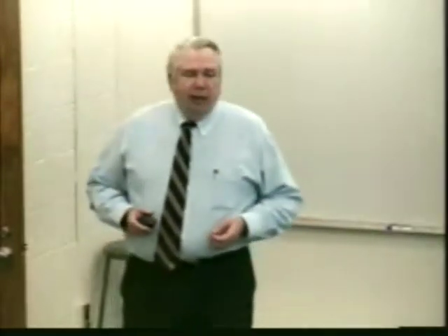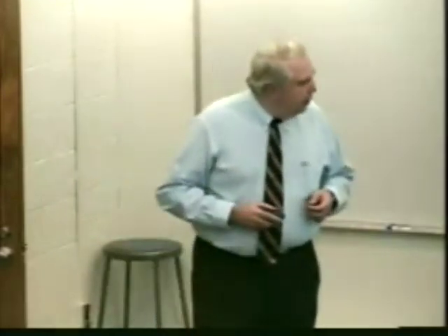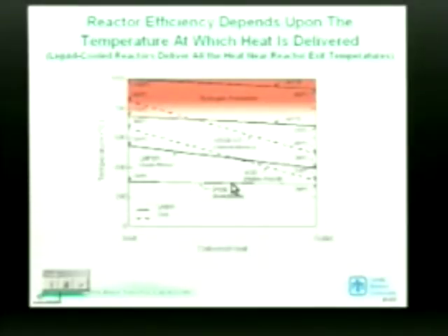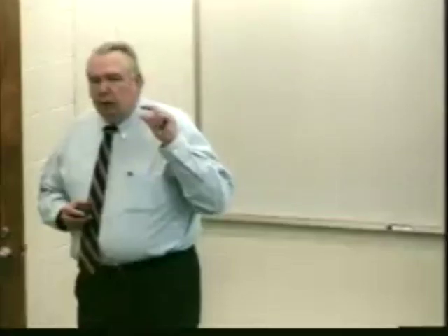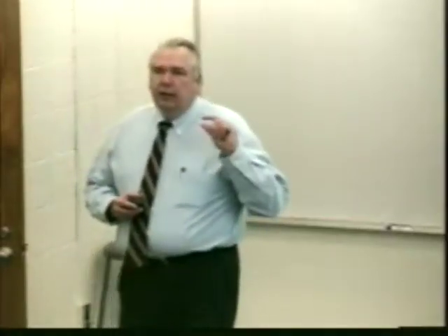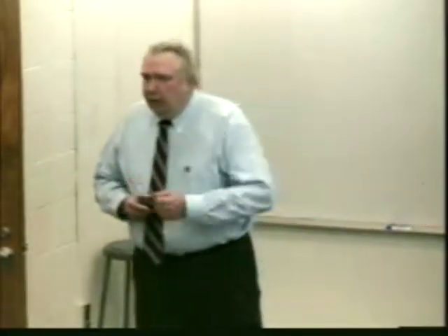Highly undesirable affair. Well, let's compare this to a pressurized water reactor, a liquid-cooled reactor. I've used this example, the Point Beach reactor, which is in, I think, Wisconsin, if I remember correctly. We find that the exit temperature from the reactor core is 319 degrees C, and the temperature going back into the reactor core is 299 degrees C. There's a 20 degrees Celsius temperature drop from the inlet of the reactor to the outlet.